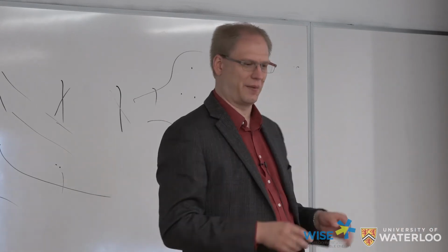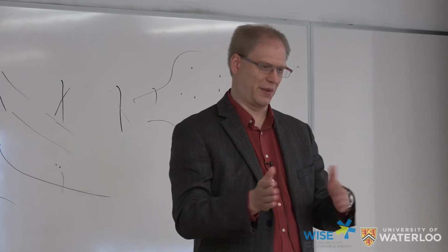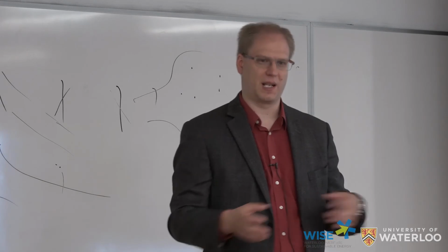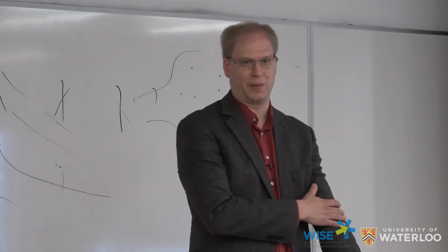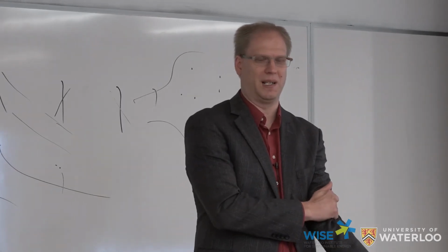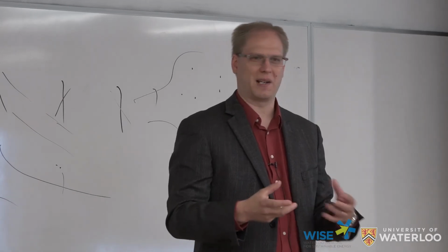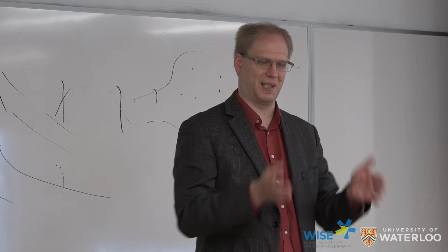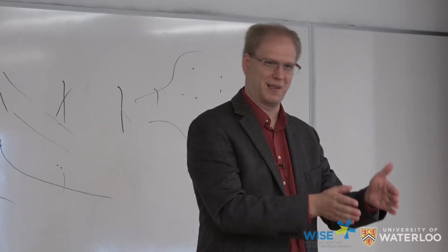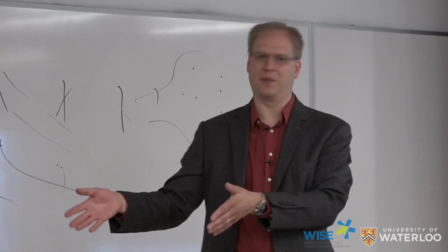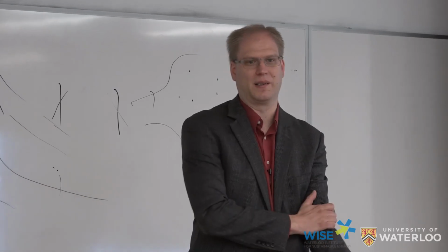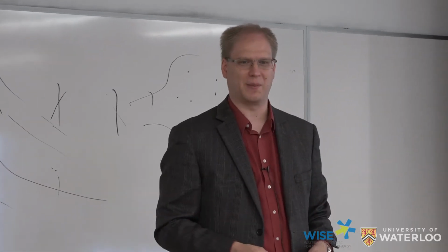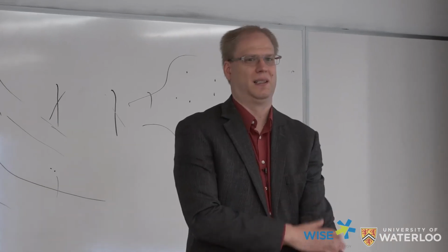So the question is, if I start looking at those different yaw arrangements and start actually doing real simulations with loads, then I can make better informed decisions on what really makes sense. Likely it won't be real-time active, at least not yet, I would imagine. Right now it's probably going to be more statistical, like I'll keep the yaw setting for this length of time, informed based on some numerical analysis like this. I won't be actively yawing time step by time step to try to maximize, at least not yet.